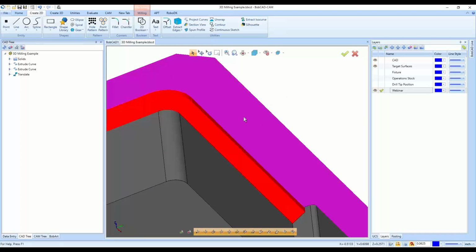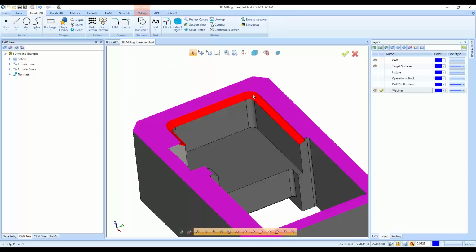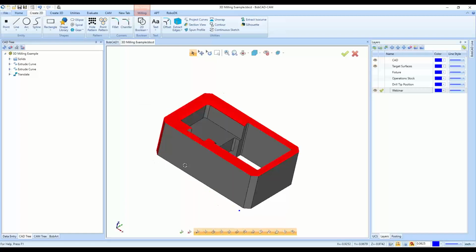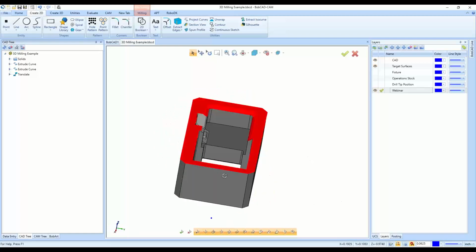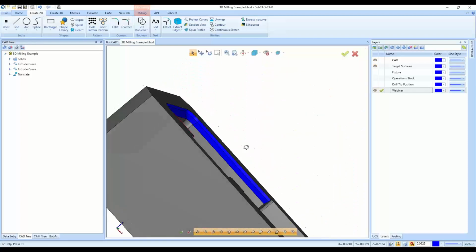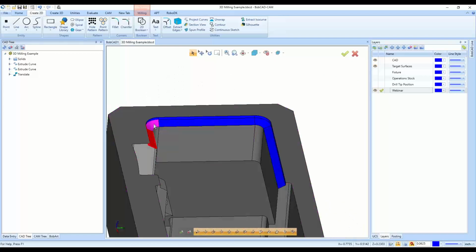And whichever one I click on and accidentally highlight that I don't want, I can just click on it again to deselect. You notice that I am selecting each surface individually. This is because if I window select one, it's going to window select everything behind it. So I don't want to do that. That is why I am individually selecting, because if I window selected this guy here, I'd be window selecting the other surfaces behind it there.